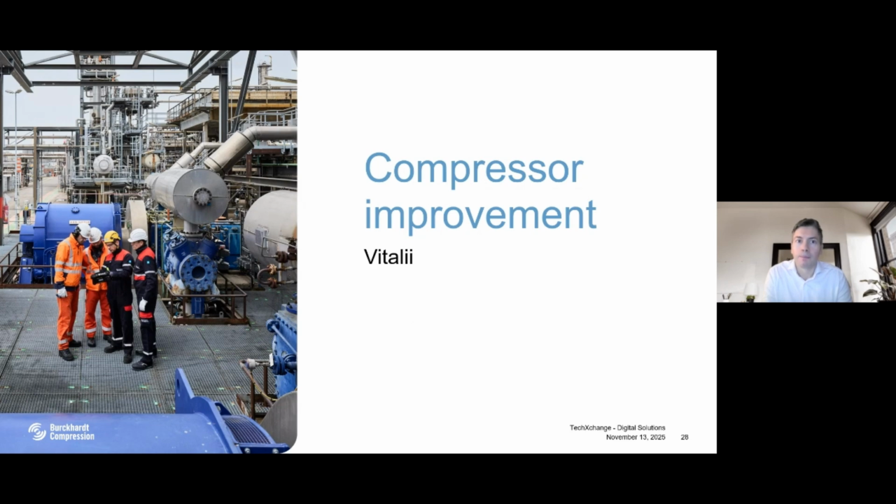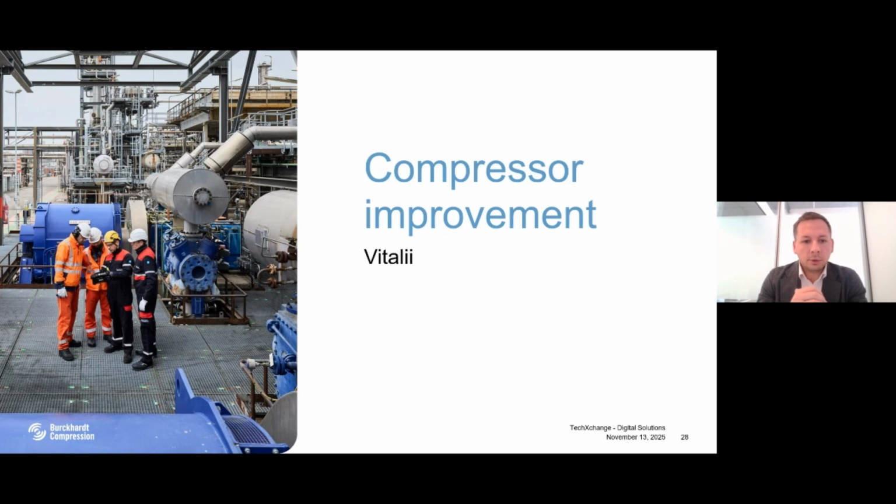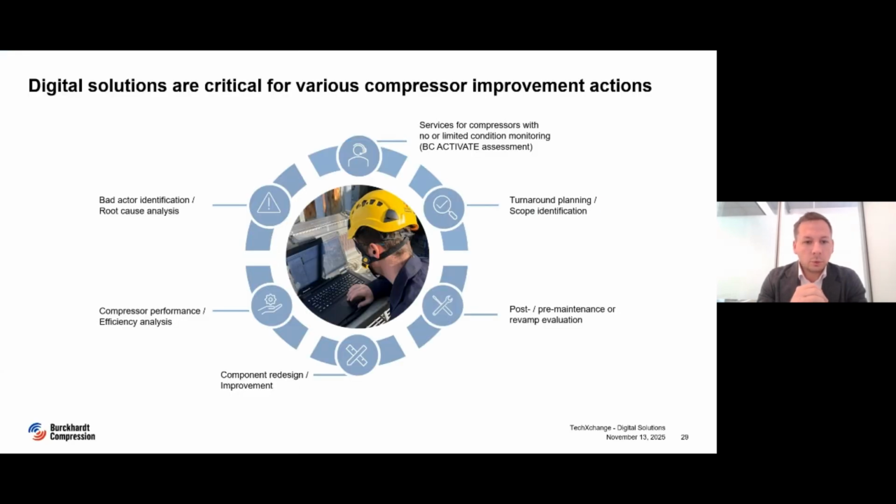Thank you, Philip. Of course, these digital and monitoring solutions represent a very good basis for us to understand the performance of the asset and bring improvements in maintenance and the design of components. Here we can see typical examples where we use these systems actively: support on root cause analysis and bad actor identification. Monitoring can provide very good data: quantitative performance analysis of compressor capacities, temperatures, pressures, and power consumed, as well as individual components such as valves, sealing system, piston rings, for example.